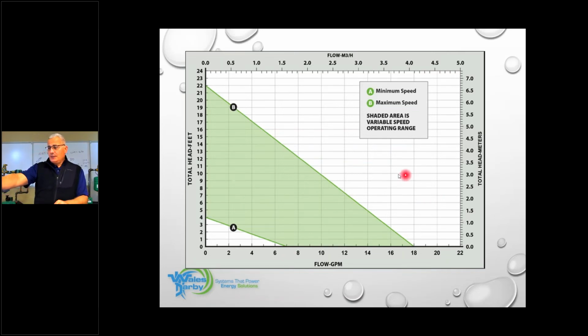And you can see here, this is a kind of different pump curve, because all it is is this big green area, and this circulator will work anywhere within this big green area. So here, it'll actually create pump curves based on how many zones are opening. So instead of following one system curve and riding along a fixed pump curve, I'll actually end up running where I need to be. So if all zones call and I need to be at 5.2, the closest I'm going to get is 5. And at 6 feet of head, this is where the two plot lines will meet right there. What will happen is it'll create this pump curve that way, and that's the way it'll run. And as zones open and close, it'll then change its speed, either picking up speed or slowing down speed to maintain that 20-degree delta. And it'll keep creating new pump curves.